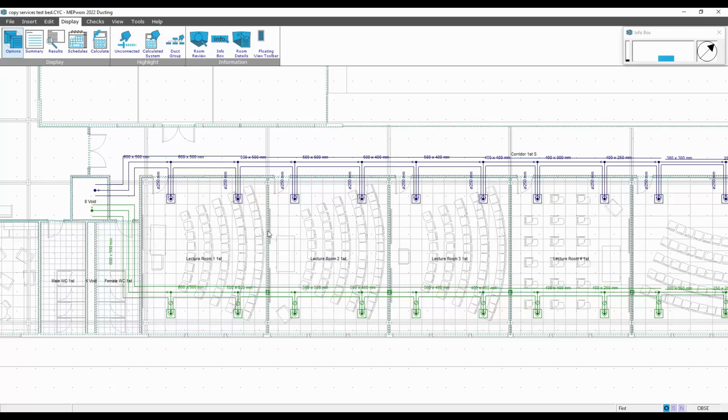Likewise with cooling, if the basis was cooling and you travel up through the building, the lower spaces may be in shade, upper spaces may not be. So there may be a modicum of undersizing. So we have checks and balances in place.